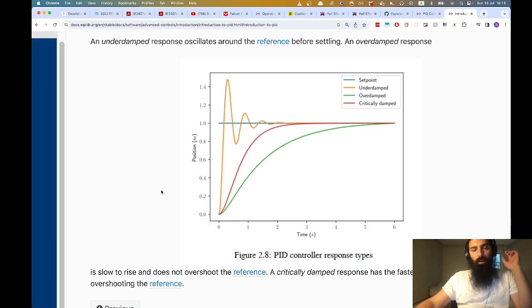And so you can code your system however you'd like. But one thing you can do is have your system under-damped, which means that it'll have this erratic behavior. That's a downside. But the pro of this approach is that you're going to get to the set point maybe a little bit faster.